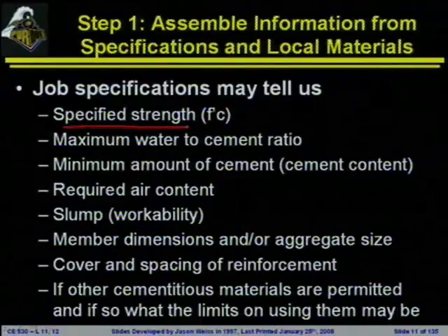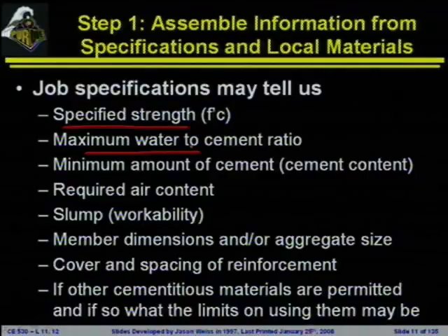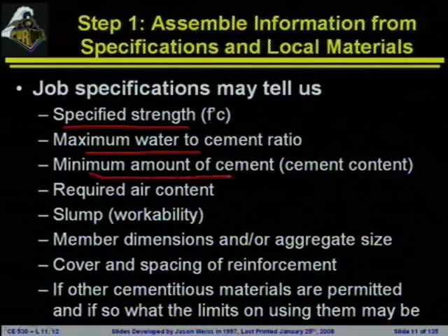They're going to give us information on the specified strength. Typically, they're going to tell us things like the maximum water to cement ratio, and that'll be dictated a lot of times by the exposure condition. They will tell us things about other limitations. A frequent limitation that you will see is a minimum cement content.